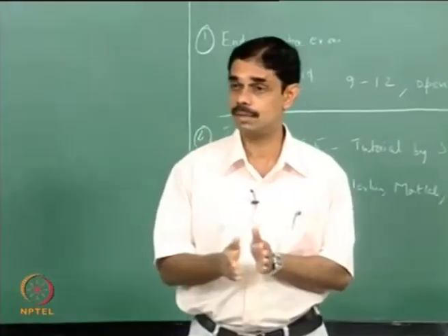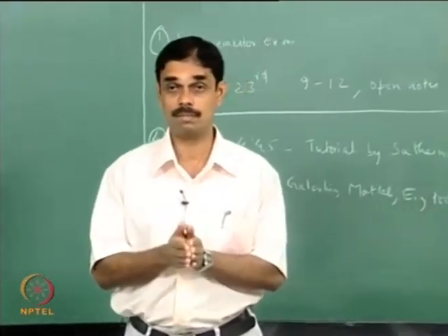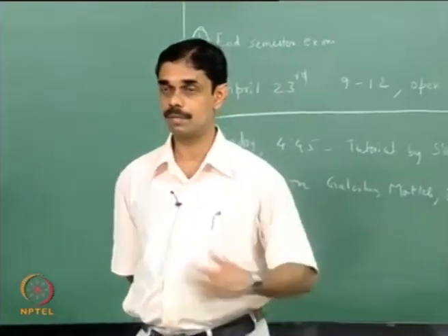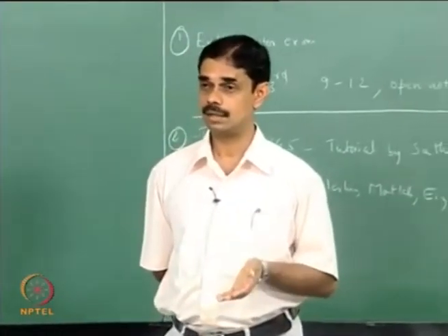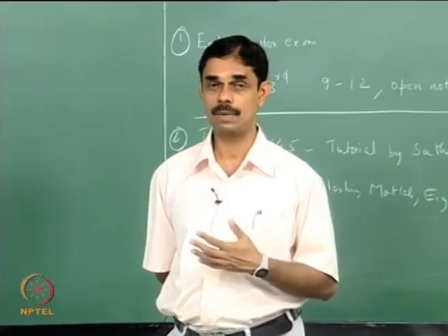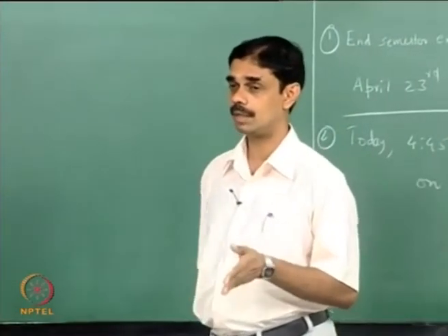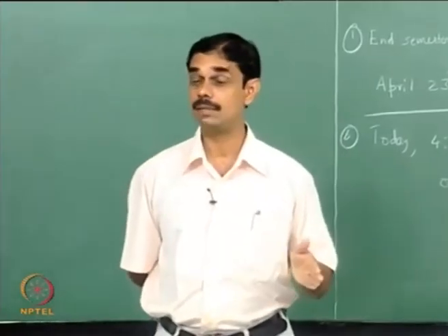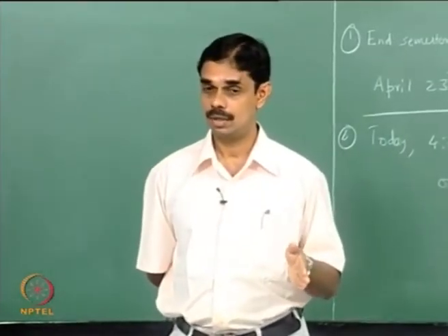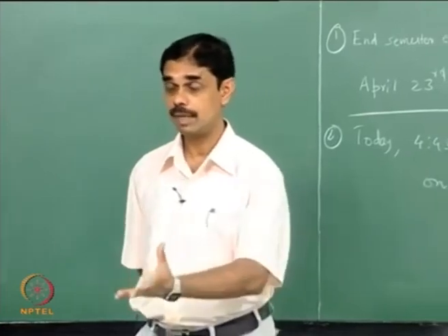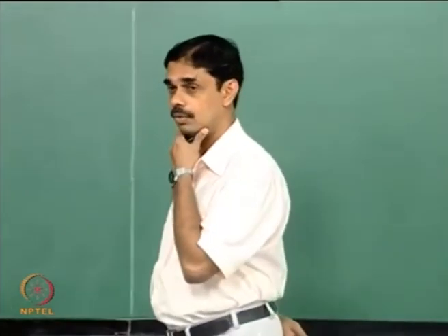Below some limit there will be a flammability limit; for a premixed flame it won't burn. People try to do premixed burners, which have low soot production, and if you burn them near the lean limit, you have very low NOx. That is what they found out. Now, can you imagine why NOx would be low if you burn lean?